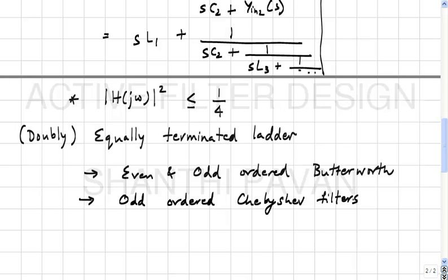So an engineering solution to this is to say, hey, I will stick to odd order. We know that if you want to design a 4th order Chebyshev, a 5th order Chebyshev will do better than a 4th order Chebyshev, and I know how to realize an odd order Chebyshev, so I will stick with only odd order Chebyshev.